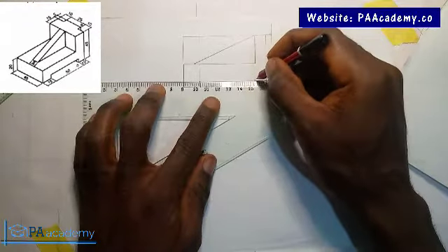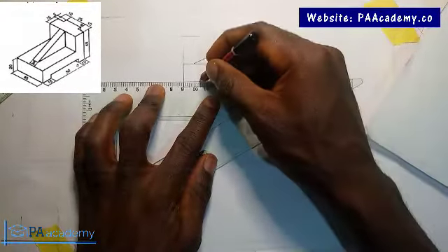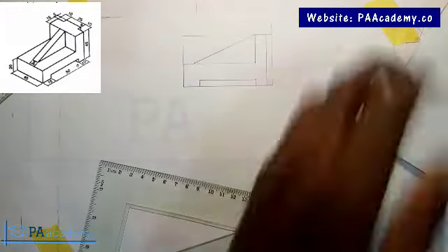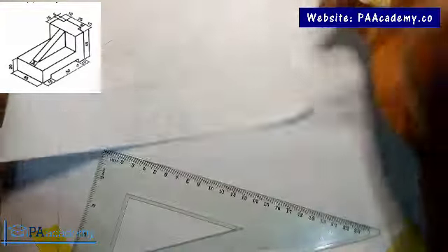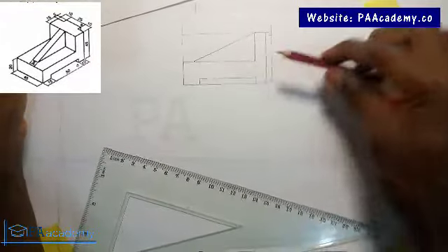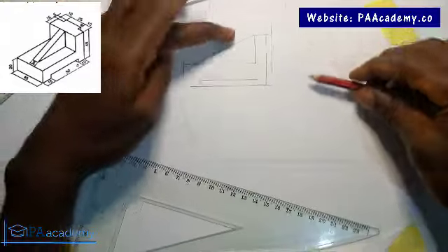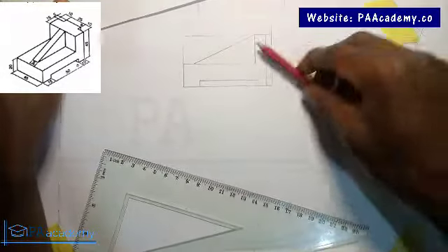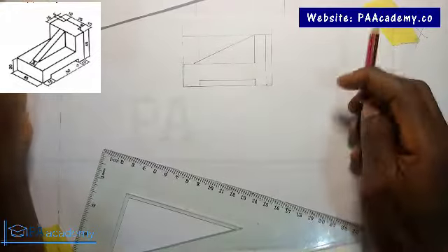So if you've watched the explanation I did on this particular first angle projection, I believe everything will make more sense. All right, so like you see, if you are looking at it directly, this is what the diagram is going to look like. Don't forget this part here. Just in case you are seeing these other lines, they are supposed to be faint lines, but the one I made bold is what we are going to see.